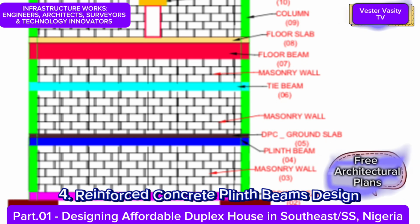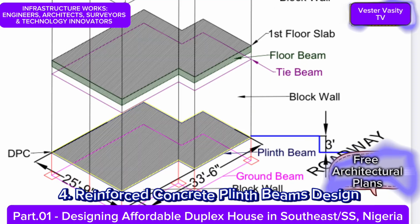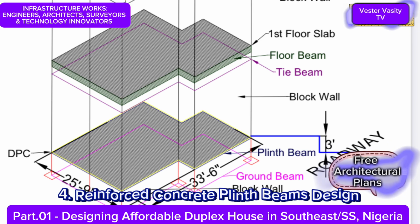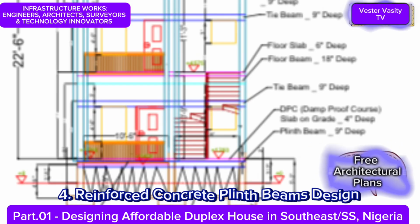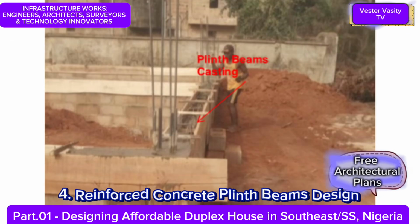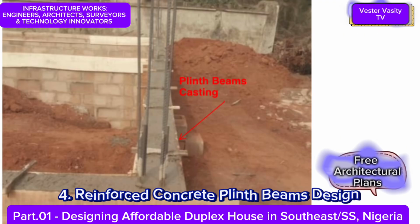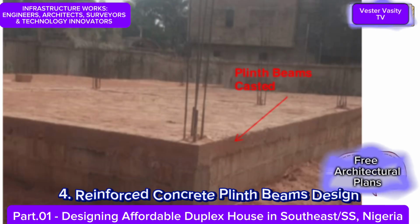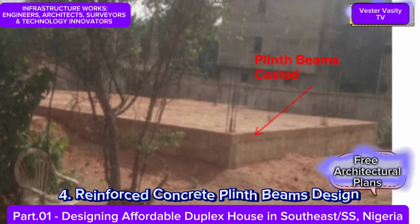The plain beams are designed to separate the foundation concrete hollow block walls from the ground level and to prevent any wall foundation settlement cracks from extending into the wall above the ground level. The reinforced concrete plain beams will be discussed separately in detail in another separate upcoming video presentation.